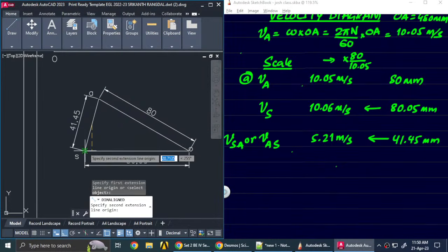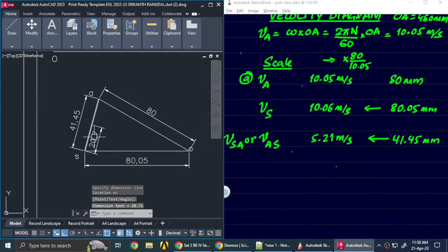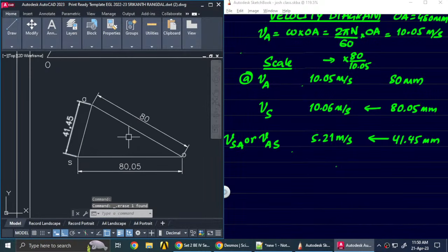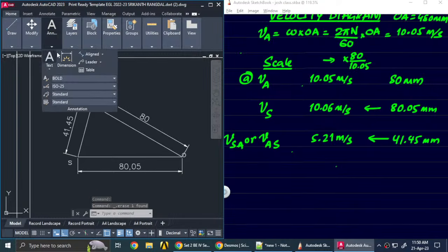So midpoint to this will give us the velocity of the midpoint of OA. Similarly, if you are asked to find the velocity in any ratio, you can take that particular ratio on this line, and that point will be moving with that particular velocity.